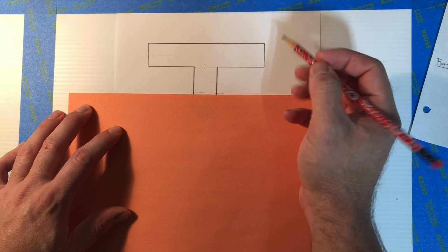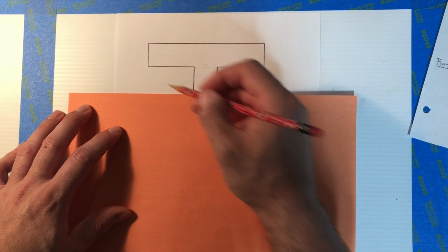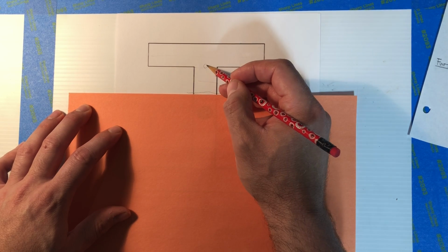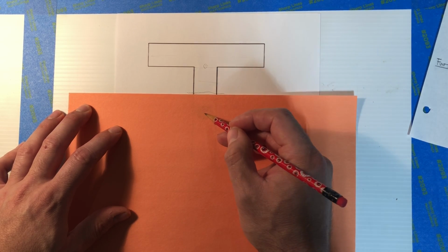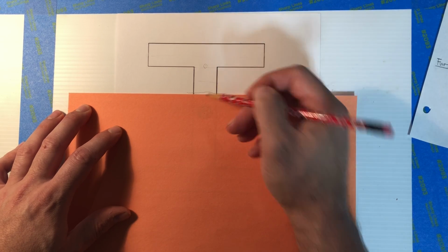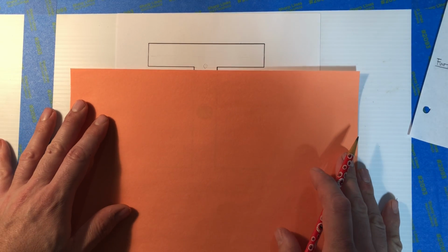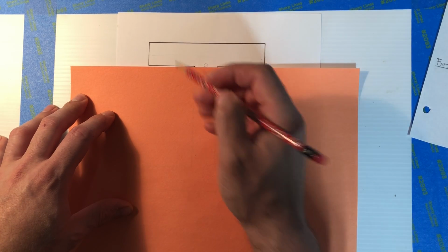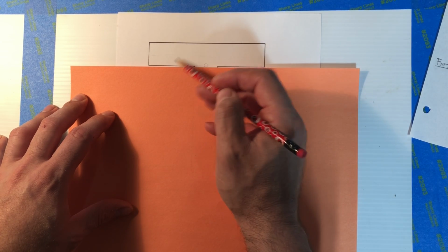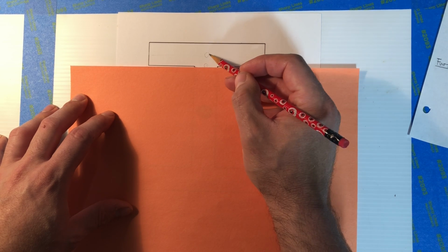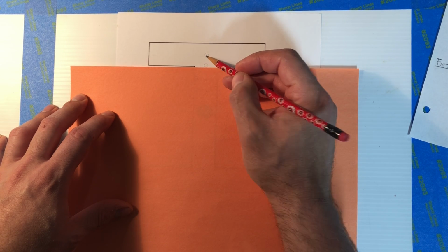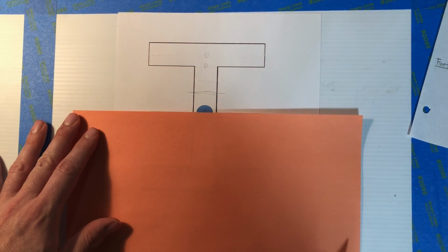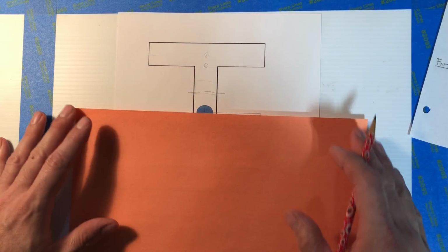Q is A_P times Y bar. A_P is all the cumulative area, and Y bar would be the distance from here to the main centroid of the beam, this whole distance. What if I wanted to find the shear stress there, right? Pretty easy. Q would be this entire area, and the centroid would now be there. That Y bar distance would be from here to the centroid of the beam. So depending on where you want to find the Q, kind of visualize it with this, right?